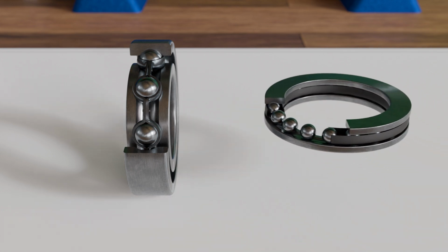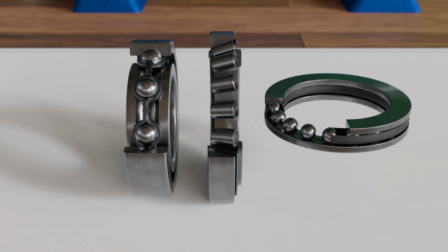Axial bearings or thrust bearings, on the other hand, can support forces that act axially along the axis of rotation. This type of bearing is used, for example, in spindles or screw drives, where components are subjected to loads in the longitudinal direction. In many technical applications, both radial and axial forces act simultaneously. Therefore, there are also combined types of bearings that can support both types of loads. However, they often have limitations regarding the maximum load capacity in one of the two directions. We will take a closer look at all of these types of bearings in this video.